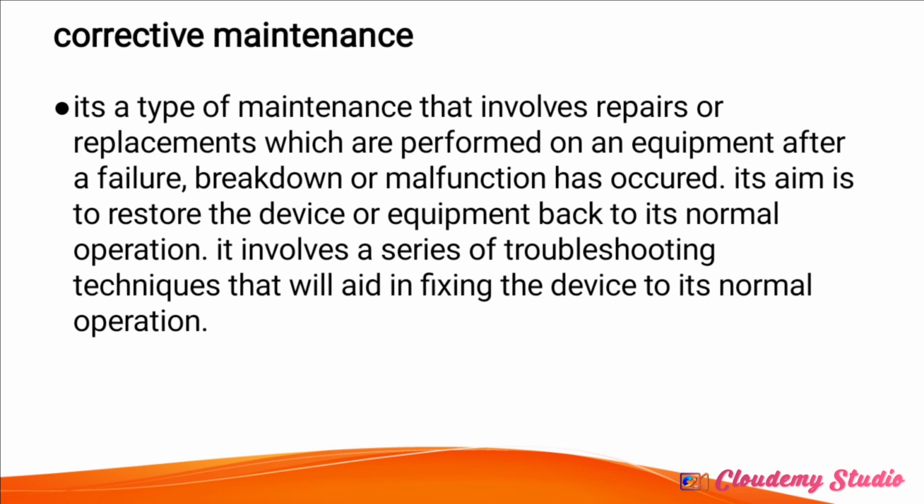Maybe there's a big failure that has occurred. So we will have to do the repairs if the device is able to be repaired, or if it's completely damaged, then we'll have to replace it. And I said in my previous class that if you are troubleshooting a circuit and you see that 85% of the components in that circuit are faulty, if it's a motherboard that is an electronic device, you'll have to replace it, because there is no other way that you'll troubleshoot one component after the other if it's 85% of that device.